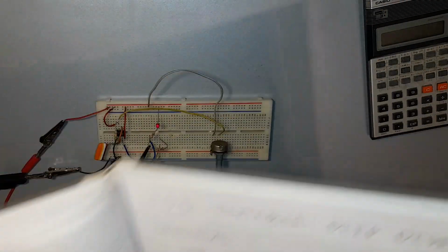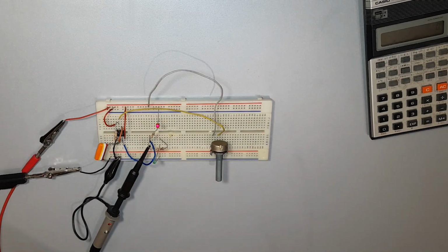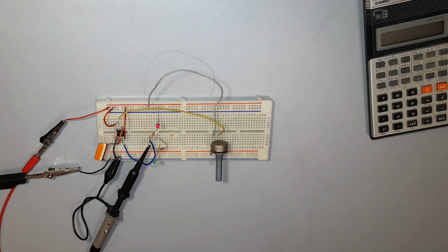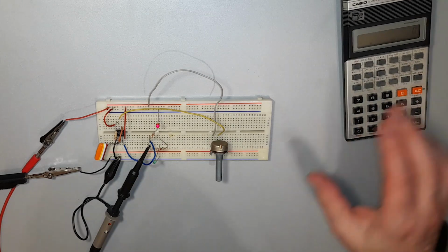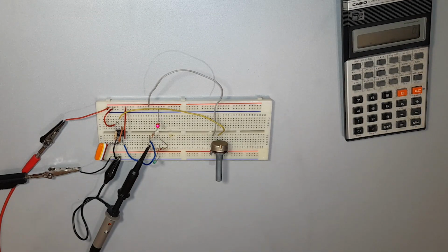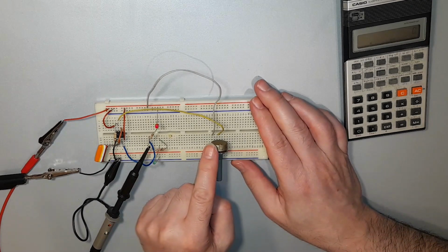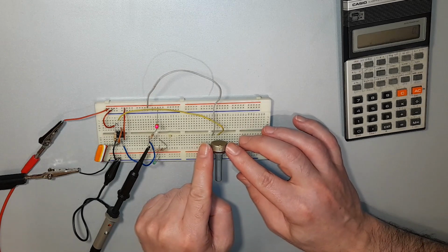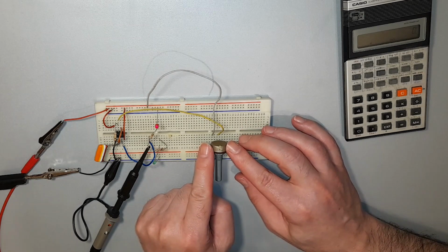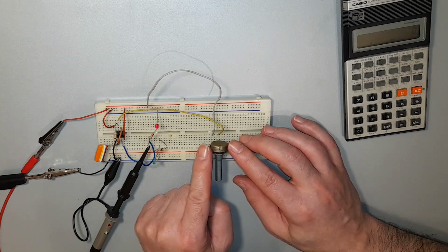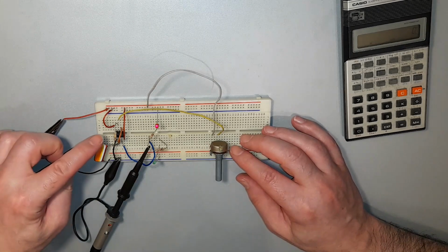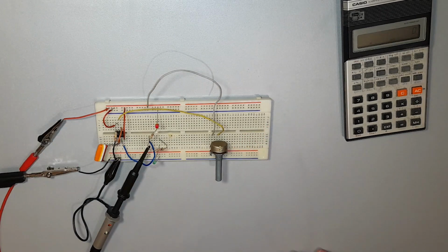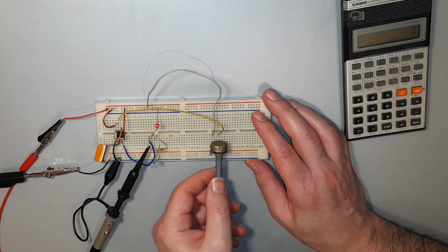We've got the ratio of the resistors comfortable now, which is that this resistor being round about 5k, or anywhere between, we found, 240 ohms and 5k, is very, very low in comparison to this resistor here, which is 100 kiloohms. So what we're going to do now is we're just going to wind this back.